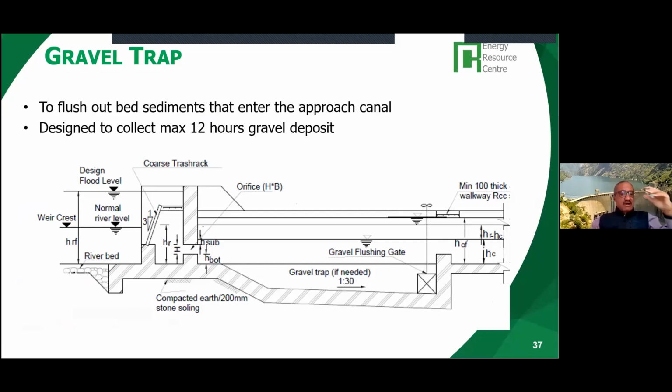Okay, now I'm coming to the design of the gravel trap. Basically, the gravel trap is required to flush out bed sediments that enter the approach canal, and it is designed to collect a maximum of 12 hours of gravel deposit.